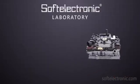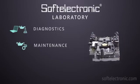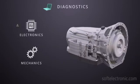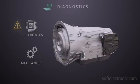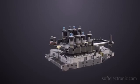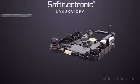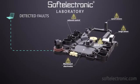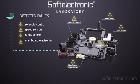In the soft electronic workshop, vehicles can get proper diagnostics, maintenance, and repair of the components in the mechatronic. If the automatic transmission is diagnosed with a problem in the electronics, the mechatronic must be dismantled from the gearbox and the control unit separated from the valve body. After that, it proceeds to the soft electronic laboratory where it's fully inspected. The client is informed on the status of the unit and the repair costs.